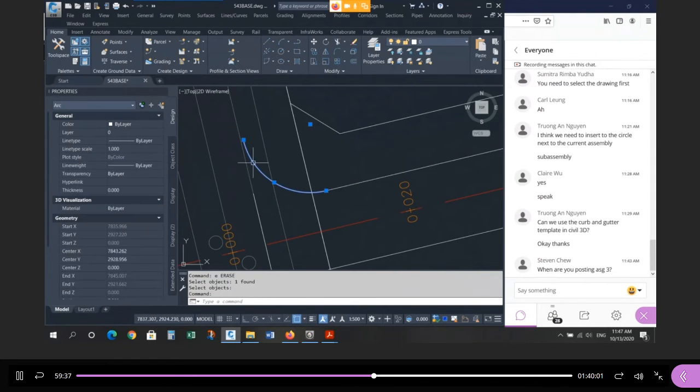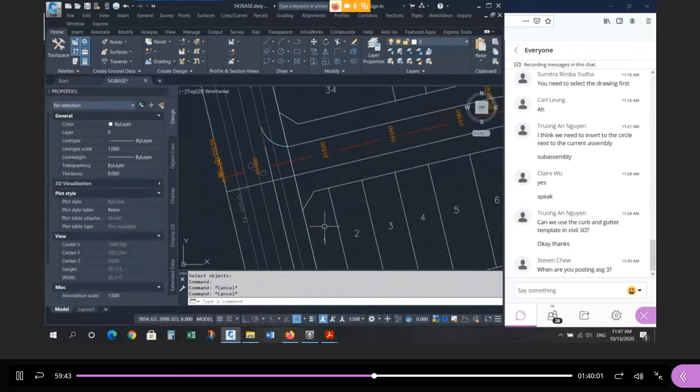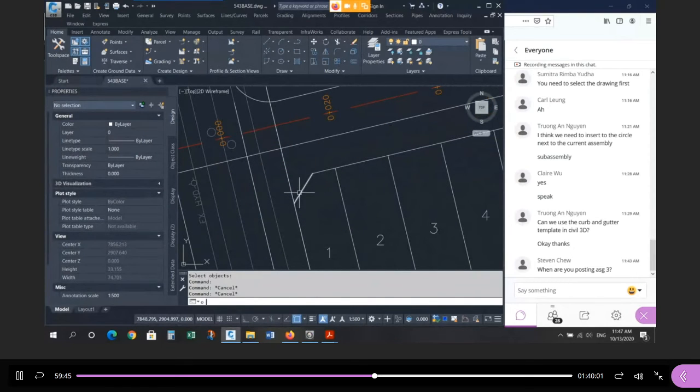So the curve comes around and the gutter is in a position so that it's 0.3 meters away from the existing edge of asphalt. You have to do the same thing on the other side. Offset 0.3. Most people got this right. And you have to do both sides separately because they're not parallel.